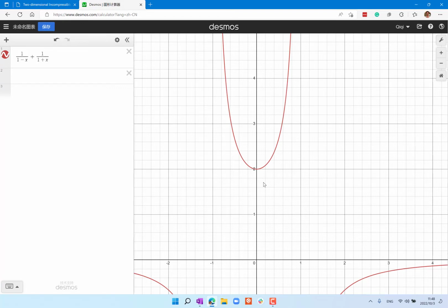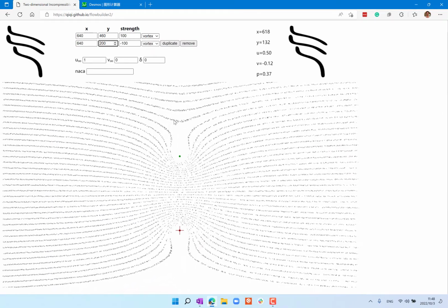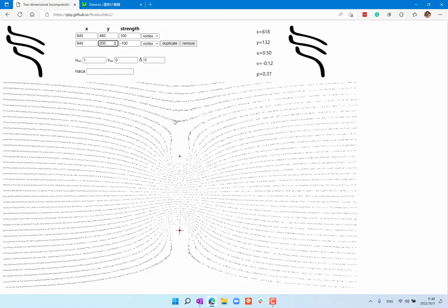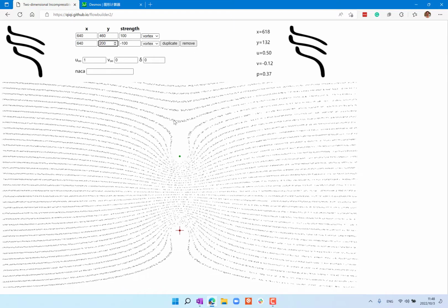That's basically a summation of two 1 over r functions. At the vortices there are singularities. The velocity due to these vortices is infinite when you get to here or here. In the middle, when you are equally far away from the vortices, you still get induced velocity, but it's the smallest. All right? Good?